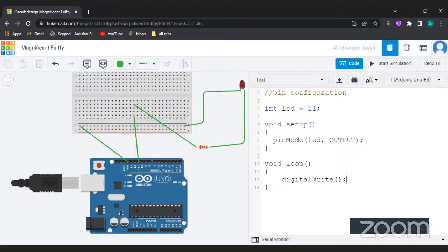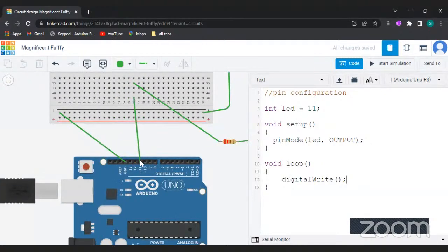It is because this Arduino pin, if you look at very well, you see this is D13, D12, D11, D10. All the Ds there represent digital, meaning that this is a digital pin. So we need a function that will actually be able to control those digital pins. So there is a function called digital write.